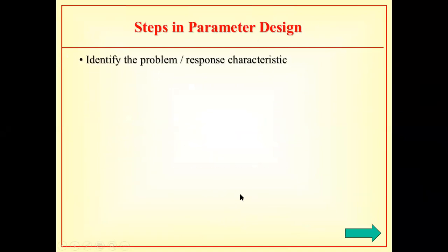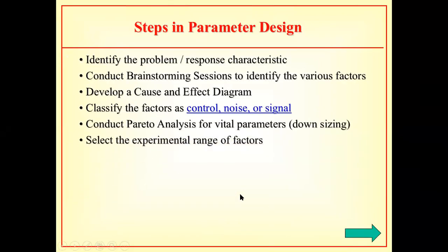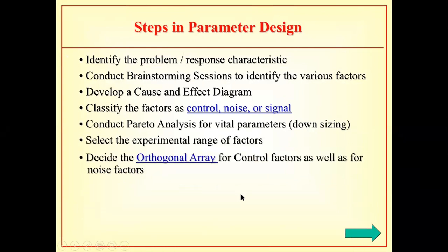So when we say decide the orthogonal array, it means the scheme of experimentation. At what setting I will do the first experiment, second, third, etc. Once you decide it, then naturally the next step is to conduct the experiments. So you conducted 8 experiments. Suppose you are measuring the surface roughness. You measure the surface roughness, eight samples are there, 8 values you have obtained.